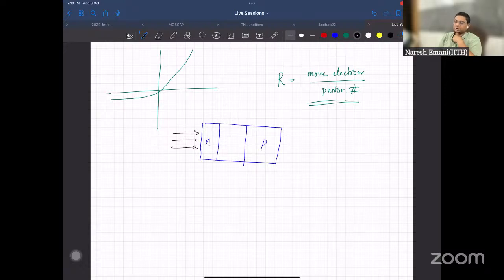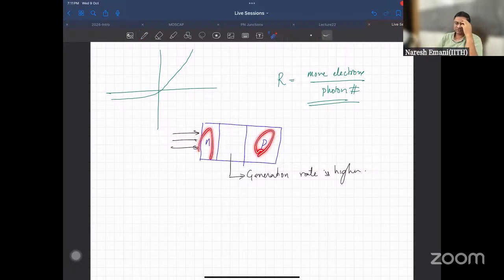Well, you could have a diffusion current. Let's assume that nothing much happens. If you look at the generation rate, it is usually higher in the depletion region. Why is that? The semiconductor tries to come back to equilibrium, correct? So in the quasi-neutral regions, you don't have much generation of electron hole pairs. Now, it depends on what kind of absorption coefficient the semiconductor has.